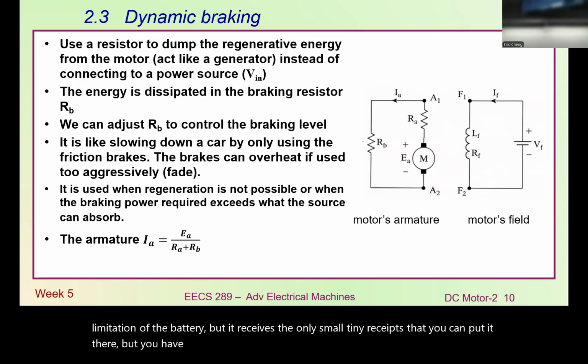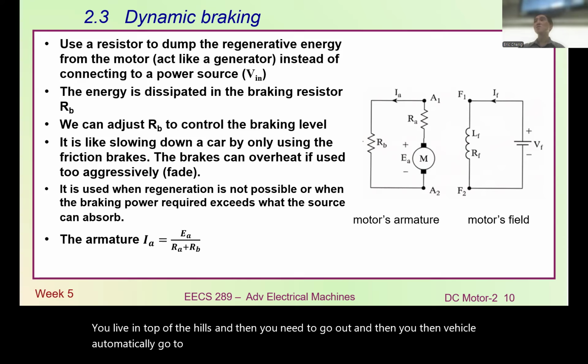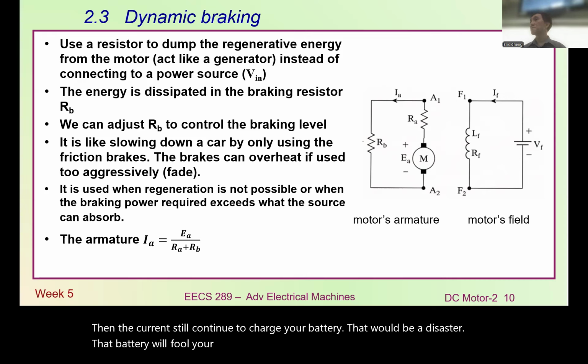In case you fully charge the battery, and then you live on top of the hills, and then you need to go out, and the vehicle automatically goes to regeneration, then the current still continues to charge your battery. That will be a disaster. The battery will be full, your BMS stops you from doing that, and then you cannot brake your vehicle.